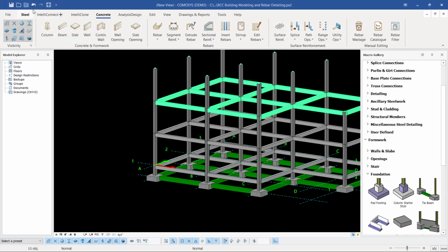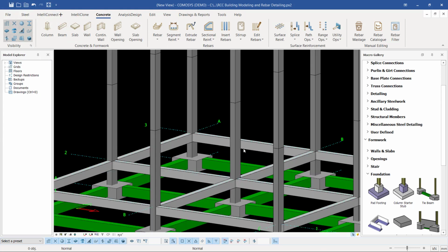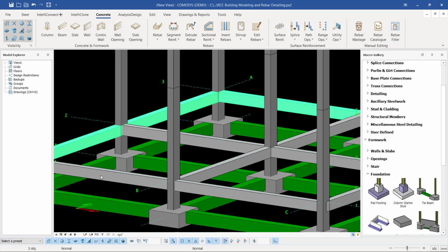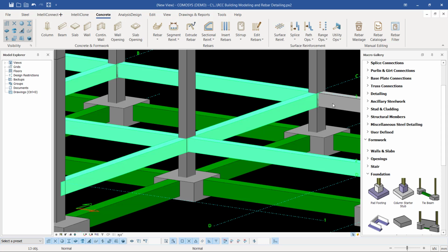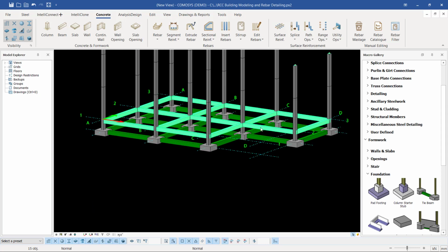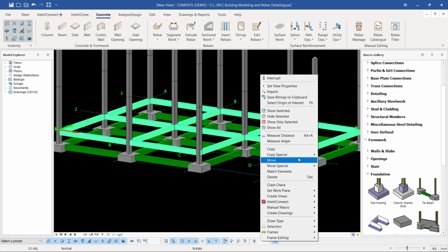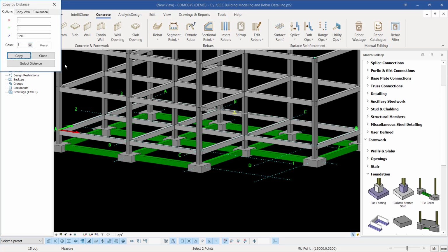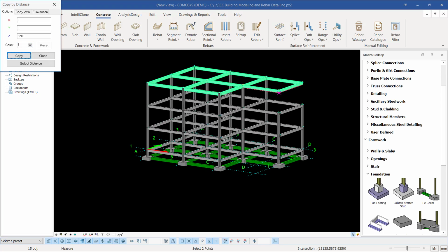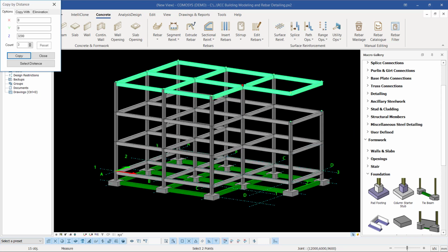I'm going to click undo and come back here and reselect, and select everything here so that we add more beams upward. Let me select that and select on that while pressing the Control button. Now I right click, come to spatial copy and pick on linear. Under linear this time, I'm going to increase that to 3. I'll click copy. The moment I click copy, before we deactivate the copy command, zoom close to see if everything has been done right. Then just click close.